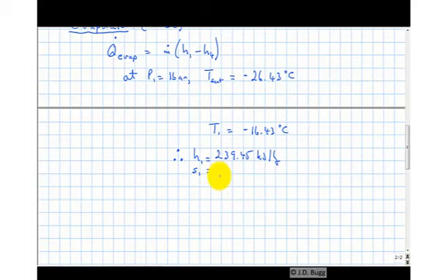And it turns out we're going to need that. So that's 0.971481. It's not the end of the world if you don't look up the entropy right away. Later on when you find out you need it, you can go and get it then. But I'll just write it down there. So we know the enthalpy at 1. So the first part of this refrigeration effect calculation at least is done.